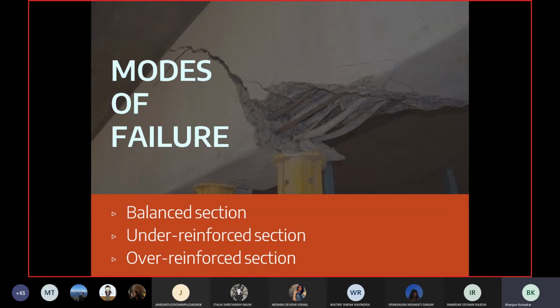So now the steel is getting strained from more and more concrete. More and more cracks are transferring their strain from concrete to steel. And now steel is moving from a passive condition wherein it was not taking any stress to an active condition. And this transfer of strain is occurring because there is a bond between concrete and steel.